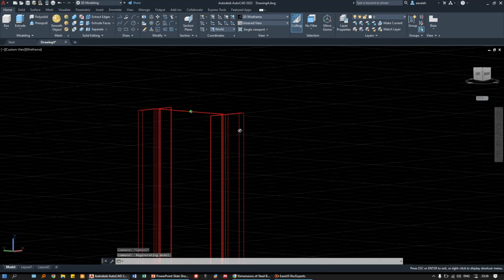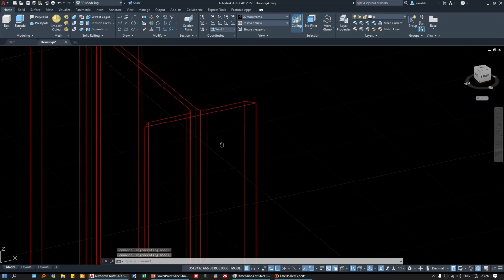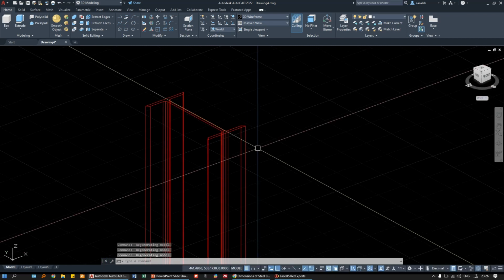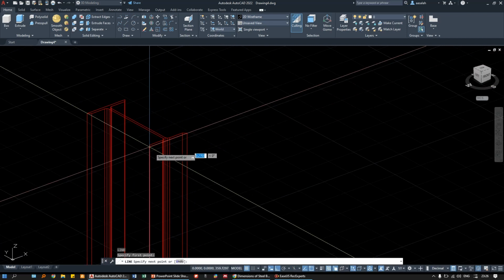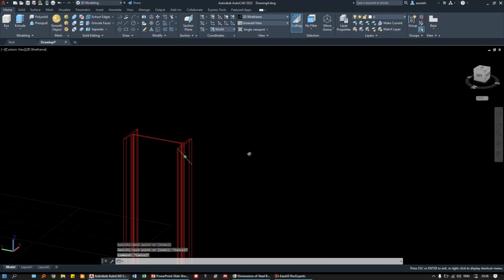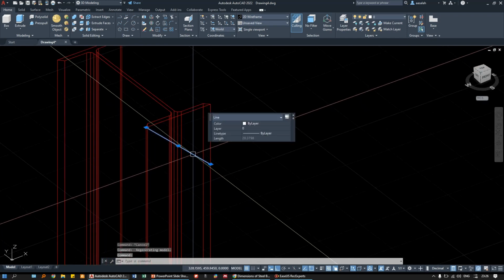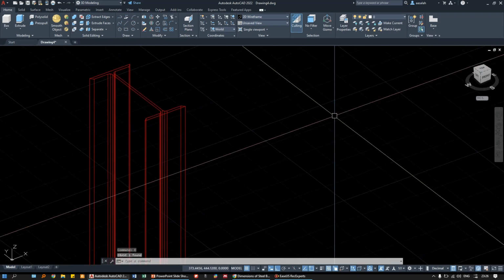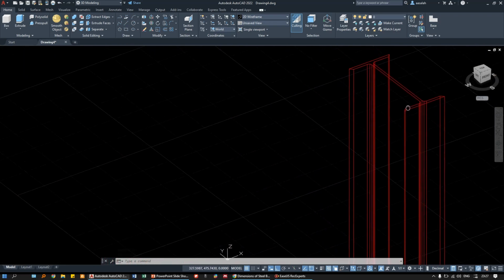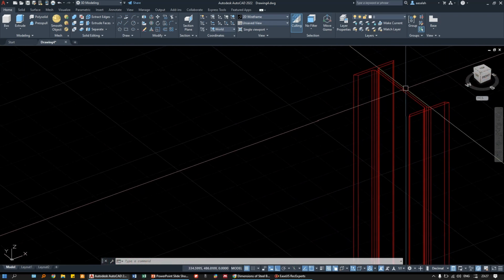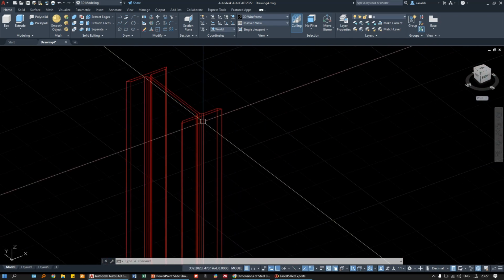So let's assume this I-beam is nice, but I want to cut this I-beam, for example, into 45 degrees. How can I do that? I mean, I need to do a cut, for example, this cut. So it's going to be cut into 45 degrees. How can I do that before drawing this line? Now, let's look at this. This is the front. When you look at your 3D model, you have also to look at this cube. So this is the top of your model. This is the front side. So let's say I'm going to work on the front side.